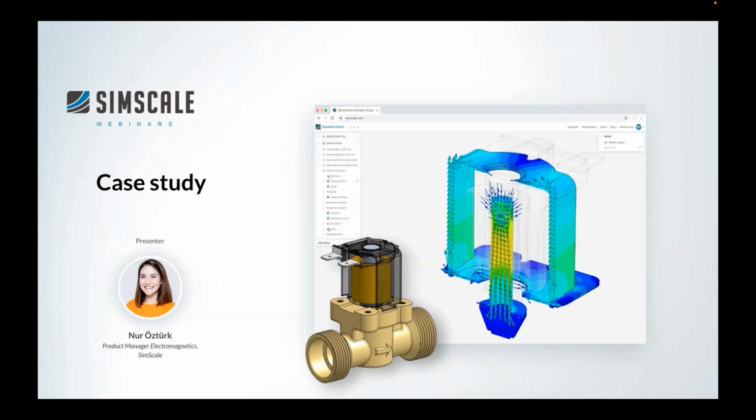So the solenoid valves are compact and high-precision components, and they sit at the intersection of electromagnetics, heat transfer, and also fluid dynamics. And their performance relies on how efficiently the coil can generate the magnetic force, and also how well the heat can be dissipated during actuation, and how smoothly the coolant is flowing through the valve body.